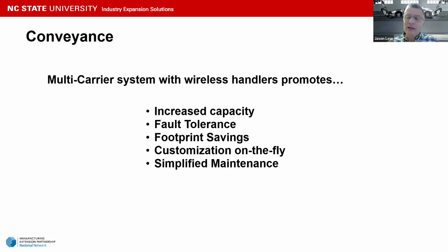So this is an example of that wireless IO-Link in this case, where the sensing and the power is being transmitted near field, right? So as these sensors on those carriers go around, they are going past a complementary sensor that is giving them instructions on what they need to do when they go down to that conveyor and need to pick something up and then need to reorient and place.